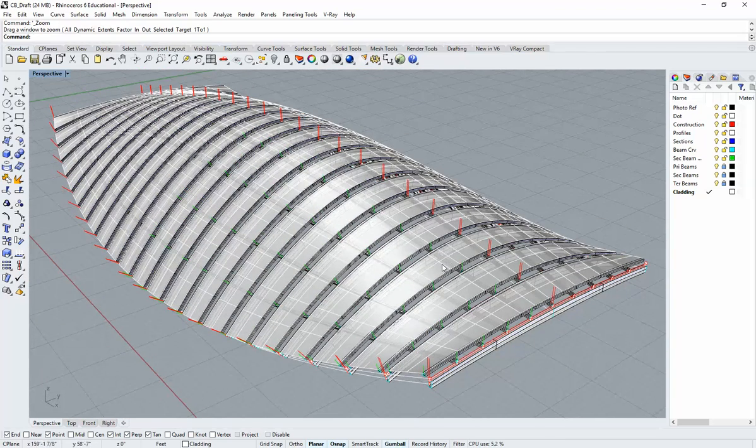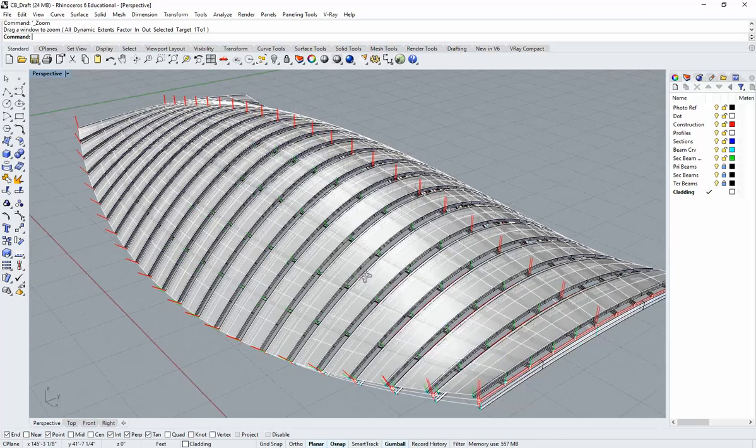The first thing we drew is the form overall using 3 lines, which is all we needed to describe this shape in 3D. And we're going to start building our sections from ground up in between. There won't be any trimming away at surfaces here. All of this is constructive. None of it is deconstructive, if you will, meaning that we're not modeling things that are larger than they need to be in order to split them or cut them later. No Booleans. This is a fully constructive model.